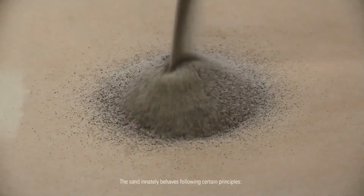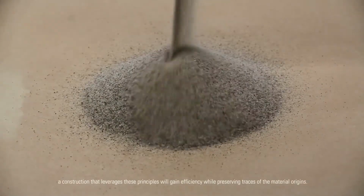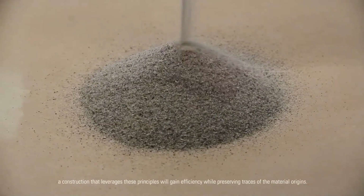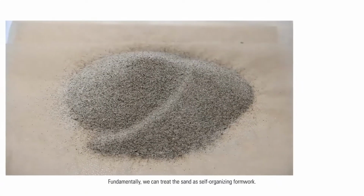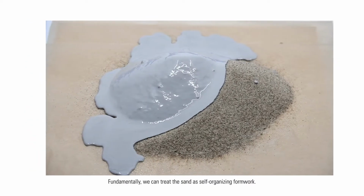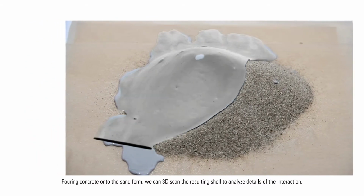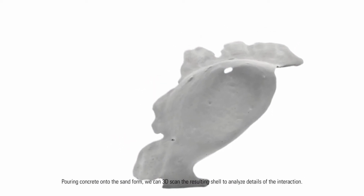The sand innately behaves following certain principles. A construction that leverages these principles will gain efficiency while preserving traces of the material origin. Fundamentally, we can treat the sand as self-organizing formwork. Pouring concrete onto the sand form, we can 3D scan the resulting shell to analyze details of the interaction.